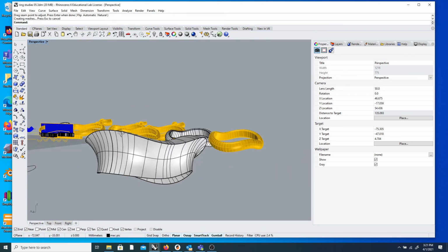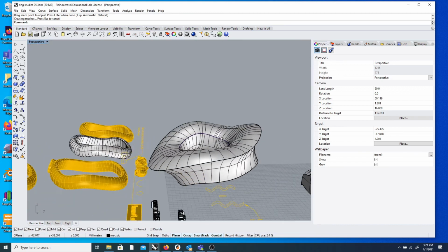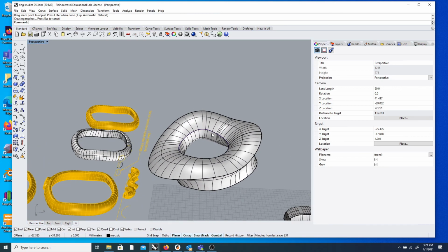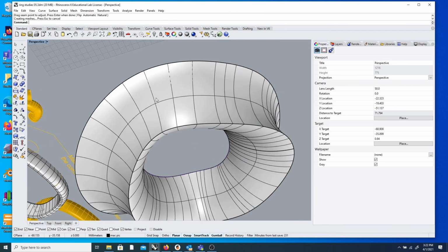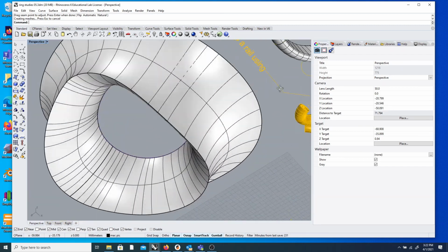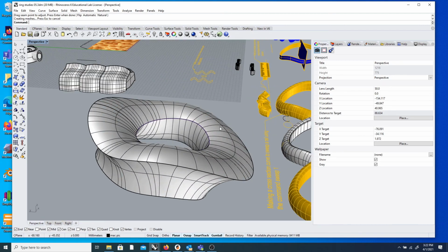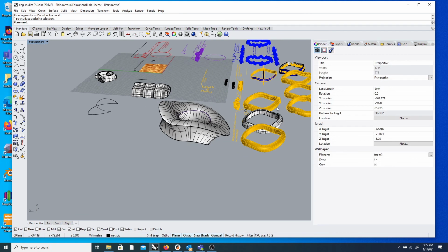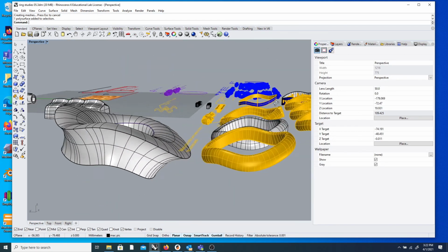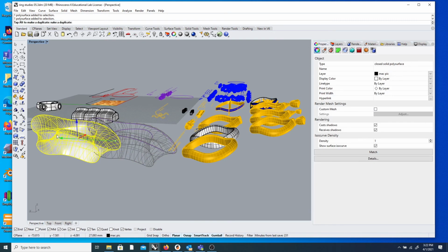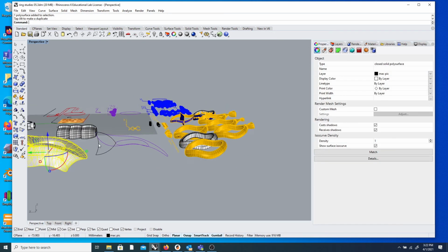So sweep 2 is when you have more than one rail. I'm using those 2 rails to drive that cross section, so it's following them. They don't have to be parallel. So that can make it bigger or thinner. It could fit into different dimensions depending on where those curves match up. But that's sweep 2 versus just sweeping. With sweep, you've got one rail, and it just goes around and matches that curve. But sweep 2, just think of it as like super messed up railroad tracks.